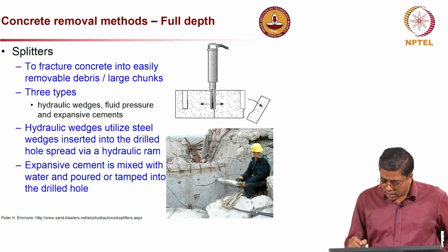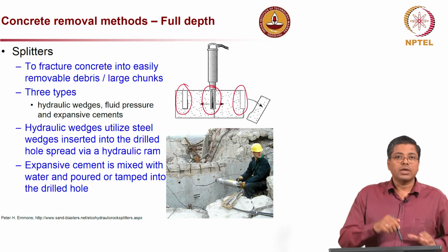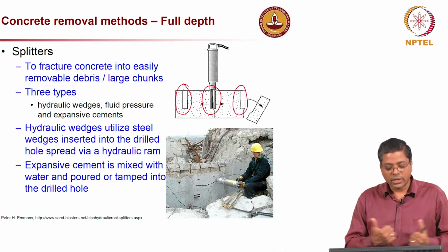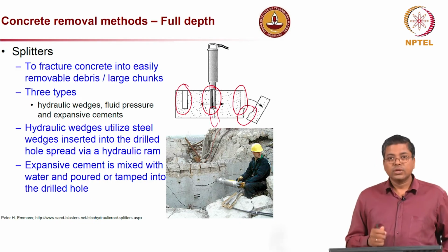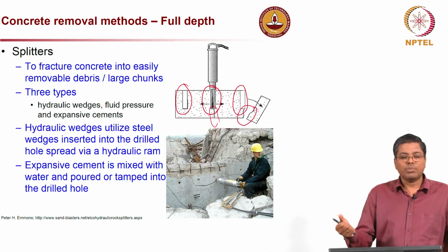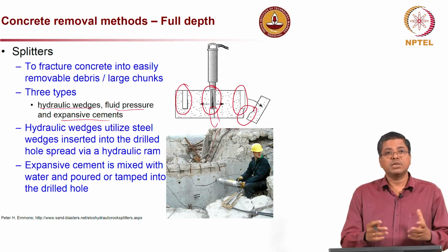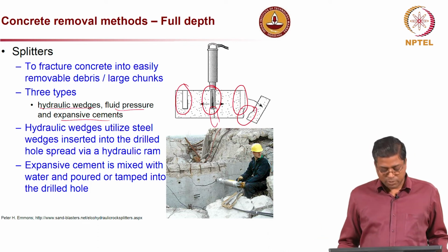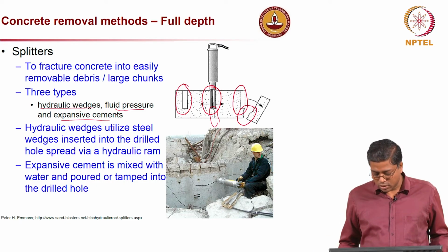Now splitters, here you can see usually holes are drilled like this, and then you insert something into the concrete, and then you exert a lateral pressure which will split the concrete, like you see here it's splitting the concrete, here also a crack is formed. So you go deeper and then provide lateral pressure either by a hydraulic wedge action or fluid pressure, or even some expansive cement which you put inside and let it expand, which creates a lot of lateral pressure, and that is how you do this.